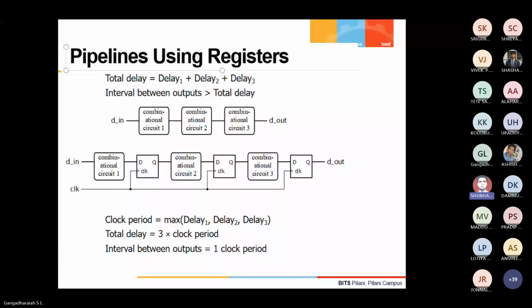If we are unable to fix timing, then only we add pipelining, correct, sir? Not exactly like that. Let's say you want to meet your non-functional requirements, that is, with respect to PPA. So you will have to play with all these things. Let's say my timing is not met. Can I do more tasks in a given time? Are you able to understand? Yes, but at the cost of more silicon real estate, of course. That's the concept behind this.